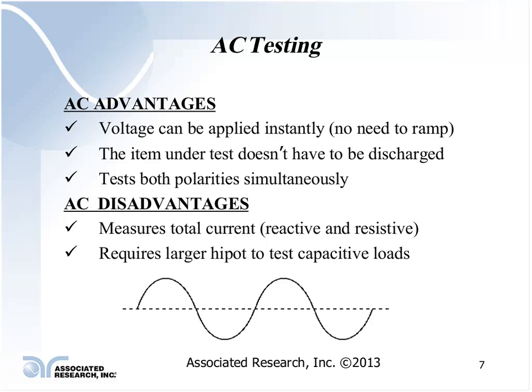requires a longer ramp time or stabilization time, if I'm just trying to read some low leakage current levels. So in doing an AC test, I don't have to ramp up the voltage. I can apply it instantaneously, so the test can be done in a shorter time span.